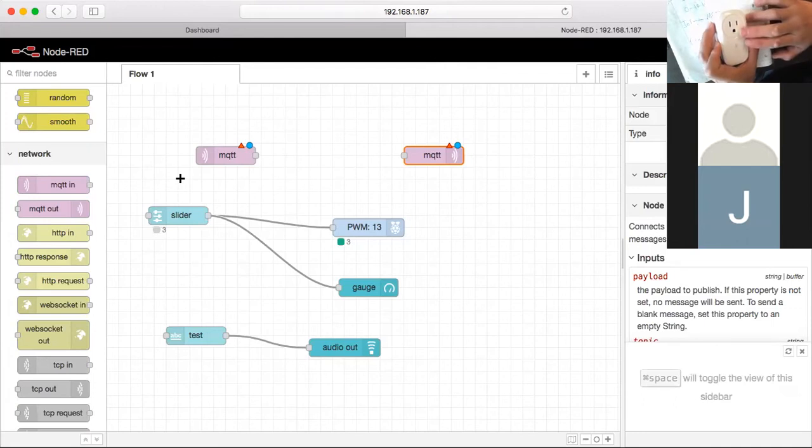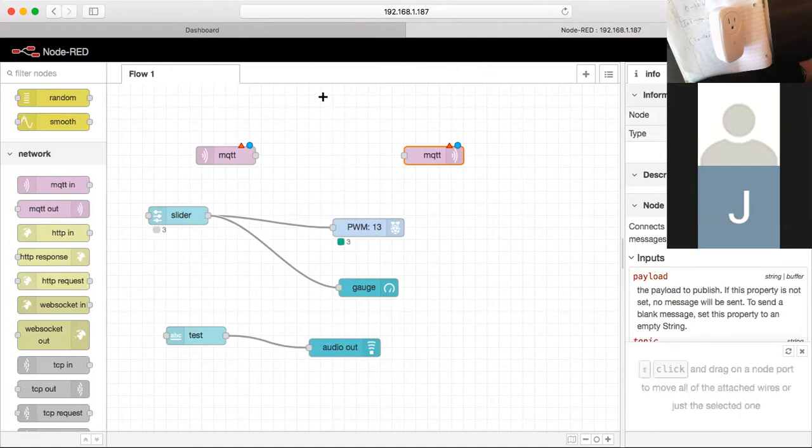You program all 10 of those and put them in various places around your house. And they can measure, for example, temperature, control lights, and do whatever you want. And then you have a Raspberry Pi as an MQTT server. And so all those computers can post and read from each other. In a way, they can communicate with each other.